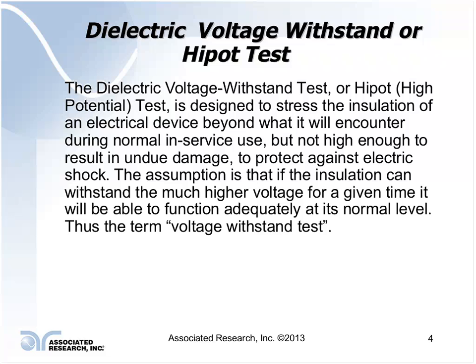It's assumed that if the insulation can pass this higher stress potential for a given period of time, it can function adequately throughout the normal life cycle of the product itself. And this is where the term voltage withstand test comes from.